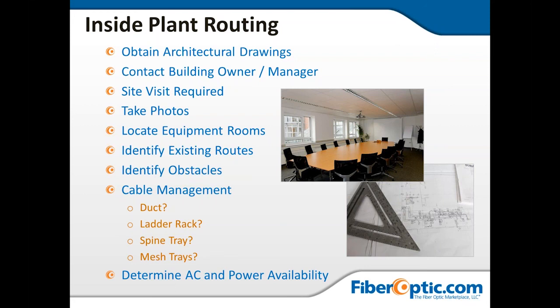And look at the future. Once you identify that equipment room, does it have the HVAC and power capabilities for today and for double or triple what you're putting in there today? Can you double or triple the heat given off by active equipment, and that HVAC still handle that heat? If you want to add more equipment, do you have the electrical power capability? Is that there? Again, it's about asking questions, looking at what you're going to need, and making decisions about today and the future.